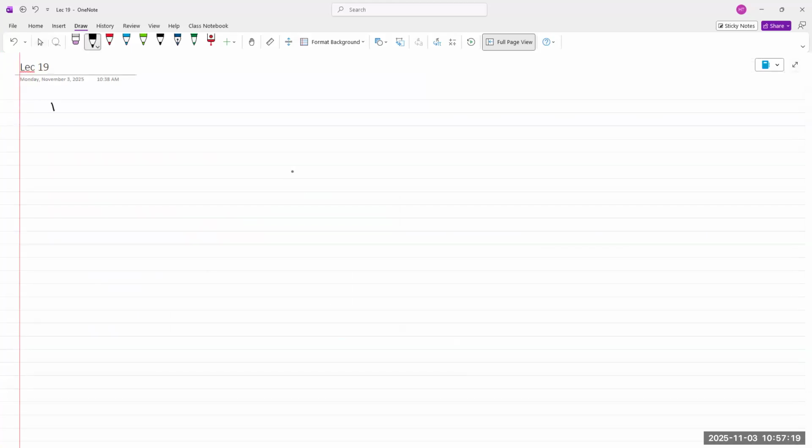So KVL and KCL still apply for AC circuits. The only thing is, in AC analysis, since we convert everything into complex number math, we represent our energy sources, meaning our voltages and our currents, as vectors that are rotating in a circle, right?